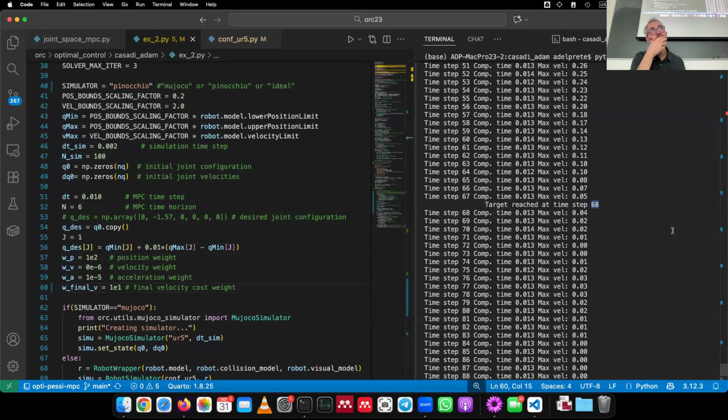Are there any other notable control invariant sets? Other than zero velocity, basically you have these three classes: equilibrium points, so zero velocities for a robot manipulator, or cyclic trajectories, in which case none of the states could be at zero velocity, maybe they're all at non-zero velocities. Or you can find backward reachable sets, since the backward reachable set of any control invariant set is also a control invariant set.